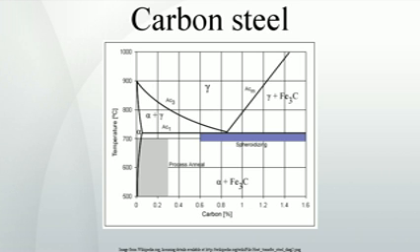Spheroidizing. Spheroidite forms when carbon steel is heated to approximately 700 degC for over 30 hours. Spheroidite can form at lower temperatures but the time needed drastically increases, as this is a diffusion-controlled process. The result is a structure of rods or spheres of cementite within primary structure, ferrite or pearlite, depending on which side of the eutectoid you are on.